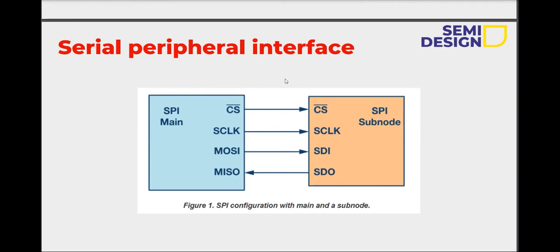What is the difference between this serial clock and the normal clock we use? This is just a serial clock, not a single clock. It is a serial clock, meaning we are using serial communication here, right? That's why it is just pronounced like a serial clock. I2C is also a serial communication protocol, so it has two lines, two signals, like a serial clock and a serial data. That is just naming. If we see APB, AHB, the signals will start with P for APB, H for AHB, like that.